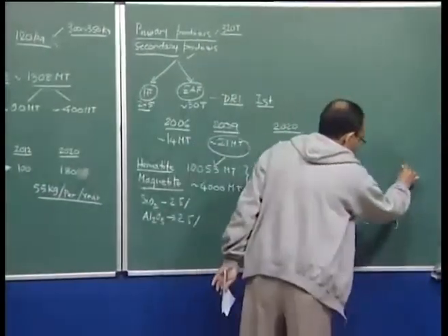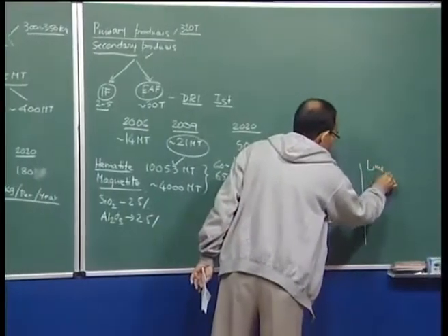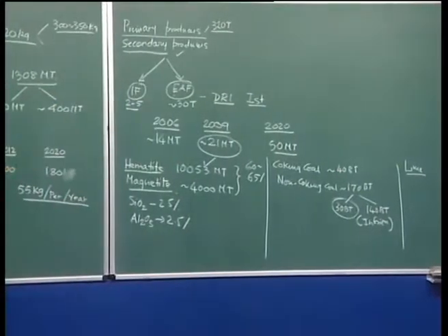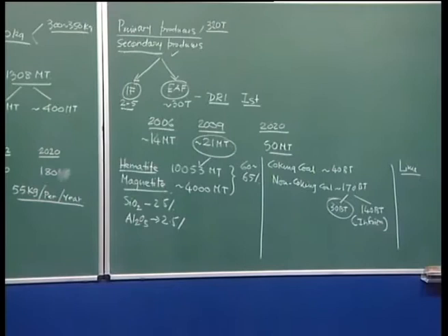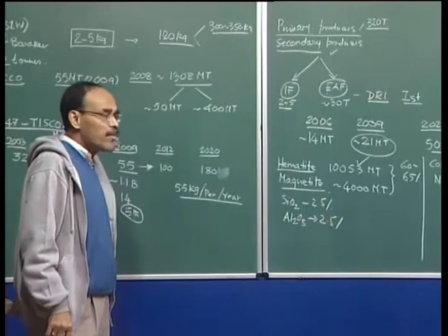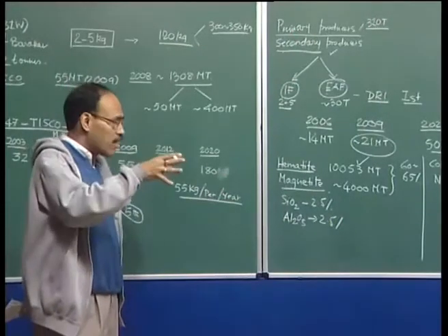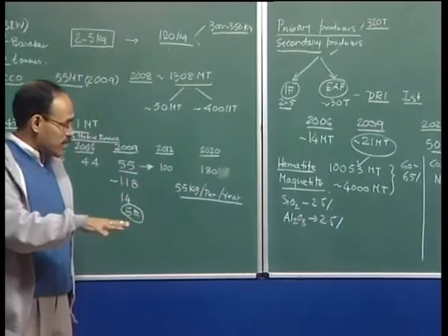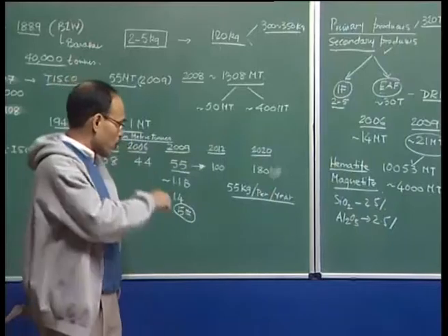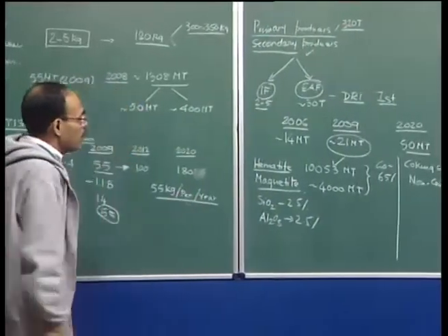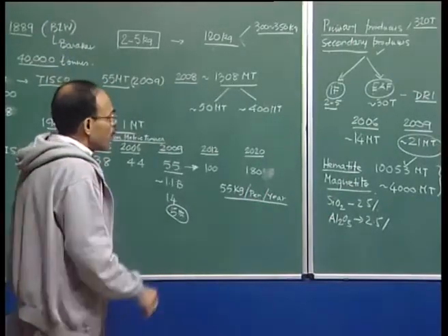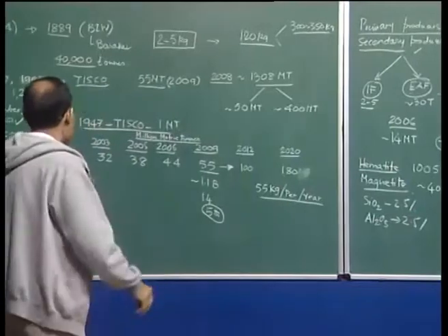We also have good quality lime or the fluxing material available in the country, but so far as Indian limestone is concerned, they tend to be a little bit hygroscopic. So that is the only demerit. But other than that, as far as the silica is concerned, this is relatively less. The lime has 50-60% of CaO, which is a very good quality, as far as the making of iron and steel is concerned.